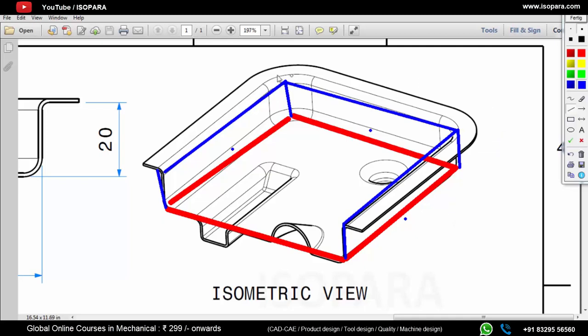Now the next step is to create a flange. So before creating a flange, we have to give rounded fillets at these corners like this. Then after creating rounded corners, we will create a flange like this. So now our base is ready.